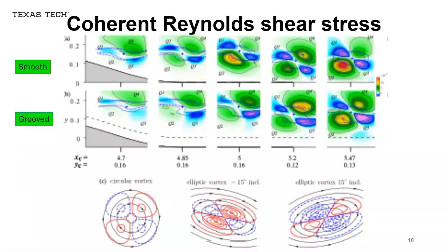Here, from this phase-locked ensemble average, we are showing some additional features of the spanwise rollers. So spanwise rollers are not actually circular, which is not a surprise. This is more like an elliptical vortex, but with a particular inclination with respect to the wall. It has an inclination where the coherent Reynolds shear stress is favoring a positive value. If we had a different inclination, we may even obtain some negative production, which was shown in other papers of our group. But the dominant form of this spanwise roller is inclined to the wall with this elliptic shape.